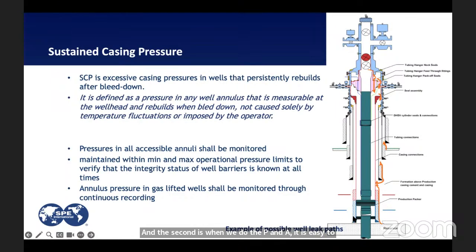But each well needs to be designed for triaxial loading and other calculations to determine the cement heights. But there is no such guidance to bring cement to the surface for all the casings as mandatory. It is good to have, but not essential.